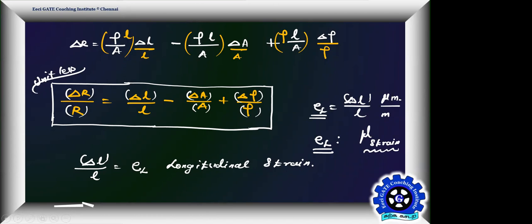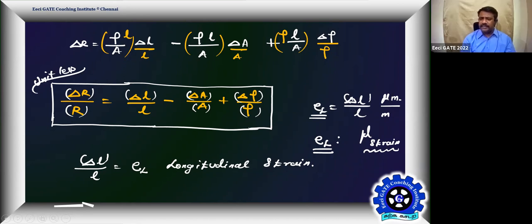Yes, sir. So we'll see what this magnitude is a little later. By default, your strain is only in the order of micro. Even if you get a milli strain, that's a huge number. Usually in the metal block, the strain will be in the order of a few hundred micro strains only.